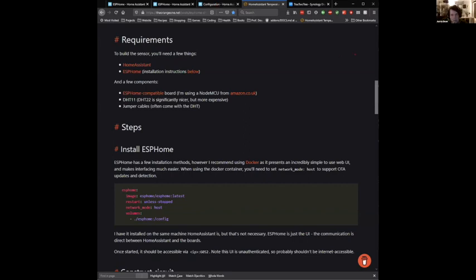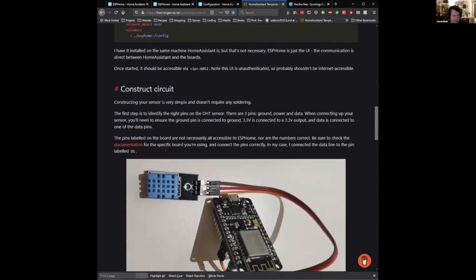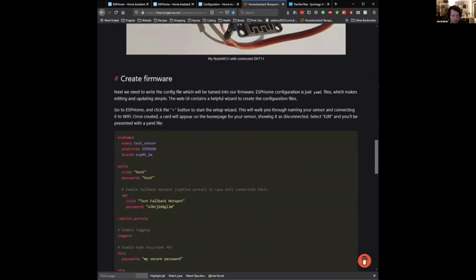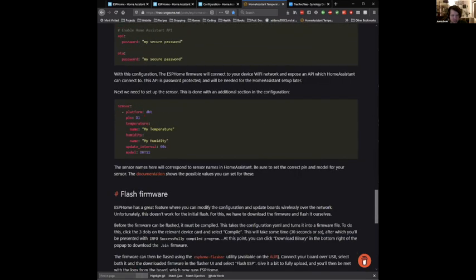It's just a photoresistor, so it's just reading an analog voltage. It's not trying to decode anything. It's not possible that it's a communication hiccup, it would just be a simple analog read on the ESP8266's side. So if I was just to plug it in and get the right pin set up, I should be able to just register it as a sensor. Yep, and I'll give that a try.